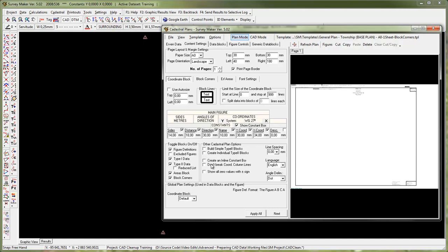So we recommend taking our base templates, setting up these settings so that it reflects on the right hand side exactly what you're looking for, going under templates, saying save template, and as soon as you save this template, these values are written into that template, and that will now become the default settings for the next time you're opening that template.